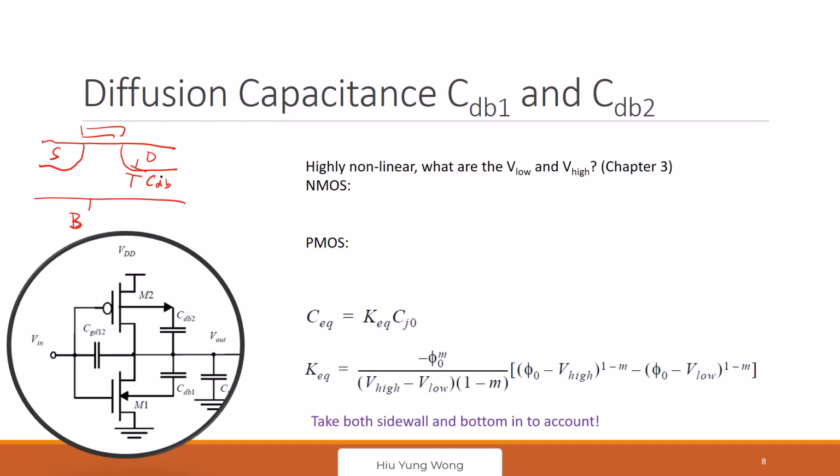Okay, now how do we calculate it? If you remember, we need to find out the region of operation, from what voltage to what voltage. I just told you that the output goes from VDD to VDD divided by 2, right? And this is VD. VD goes from VDD to VDD divided by 2. But VB is always connected to VDD for the PMOS, and this VB is always connected to ground for the NMOS, right? So for NMOS, what will happen?